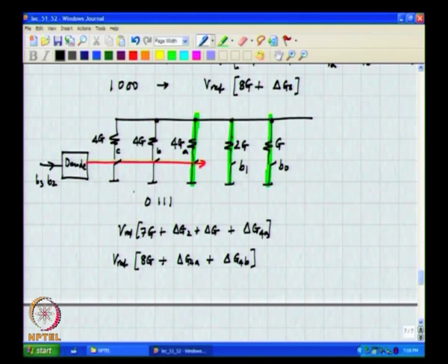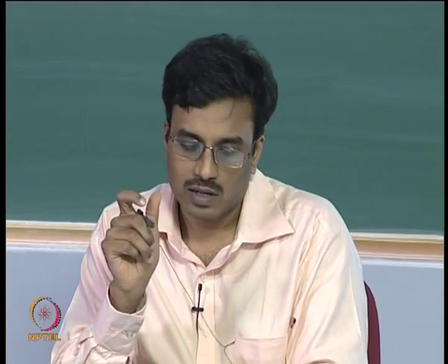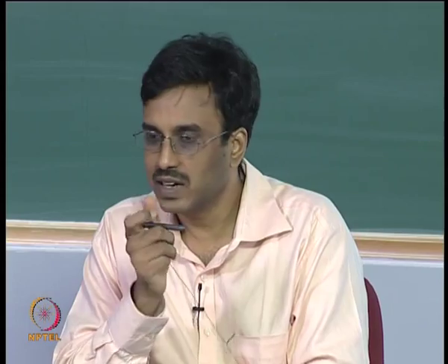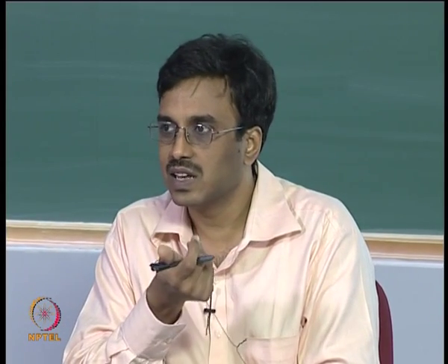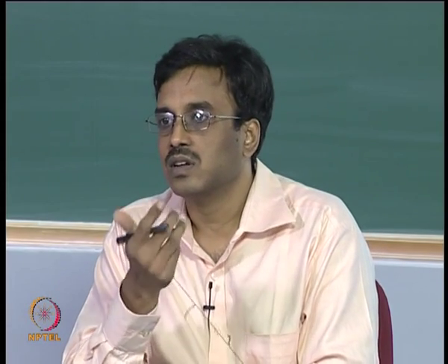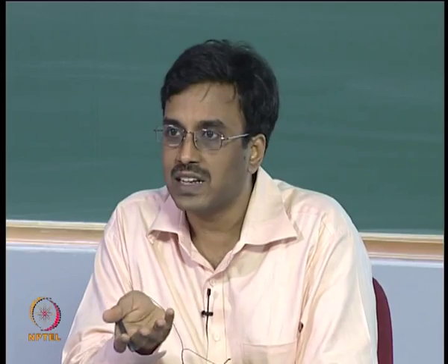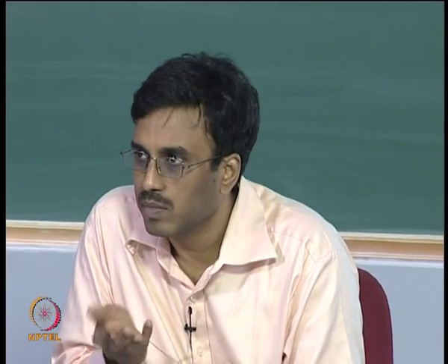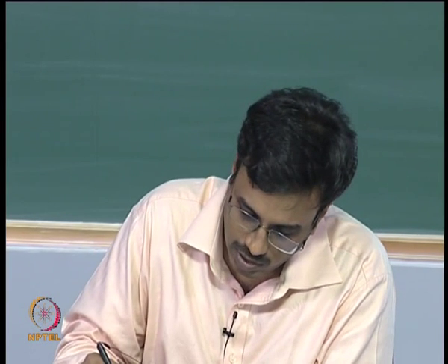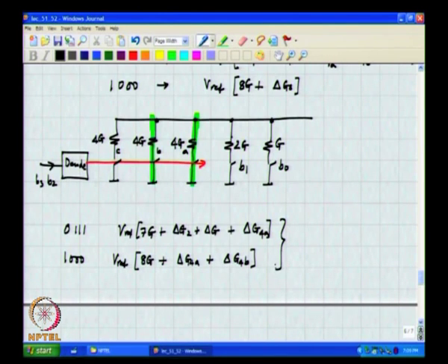So, what is happening when the code becomes 1 followed by all zeros? This is getting turned on and those two are getting turned off. You understand? Here also there is a difference, since G is realized as a difference between two large numbers. However, those two large numbers are not quite as large as they would have been if I did a complete binary decoding. Is that clear? That will become apparent when you do the subtraction. So, what is the difference?